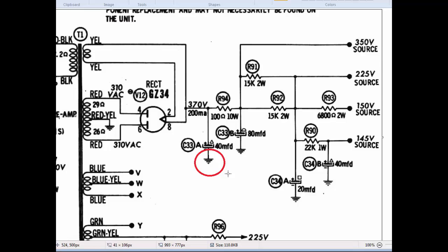It stands for 0 volts potential, and 90+% of the time, almost all the time, but not every time, the chassis of an amplifier, the metal chassis, is also at ground or 0 volts. In other words, that chassis is what you're using as your 0 volt reference, and it also is fed through your house wiring back to actual earth ground.